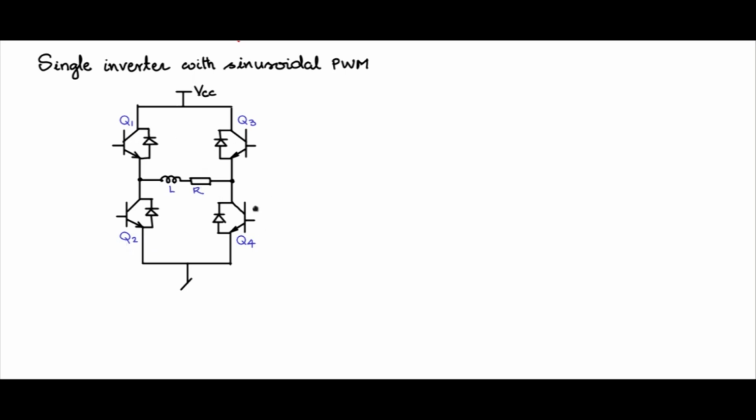This full bridge converter, depending upon the way you modulate it, could provide a DC-DC converter if you put a transformer with center tap secondary. In this case you are putting an LR load, so the voltage across the center points of the bridge will be AC voltage. Now we want to get a special quality of the AC voltage. We want an AC voltage which has a fundamental of 50 Hz sinusoidal, so that when you filter it out, you get back your fundamental sinusoidal wave shape.